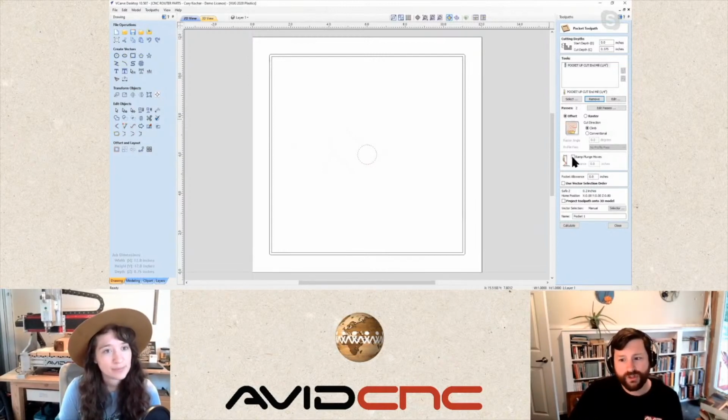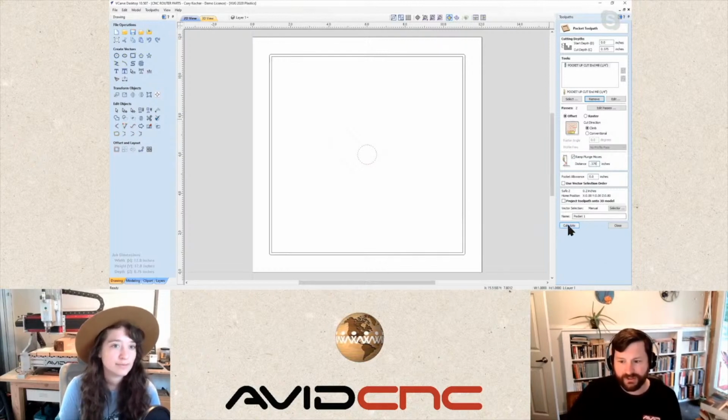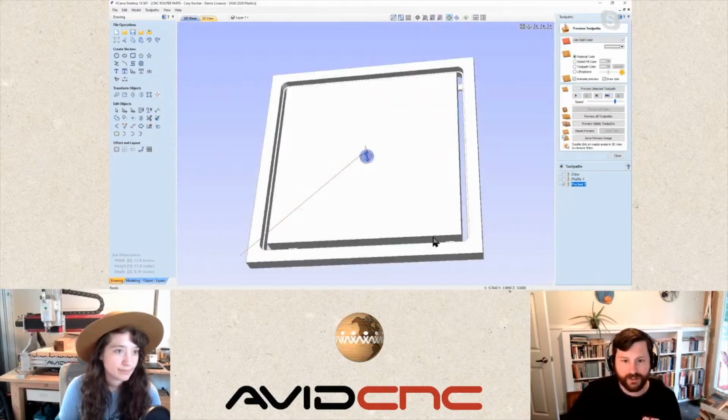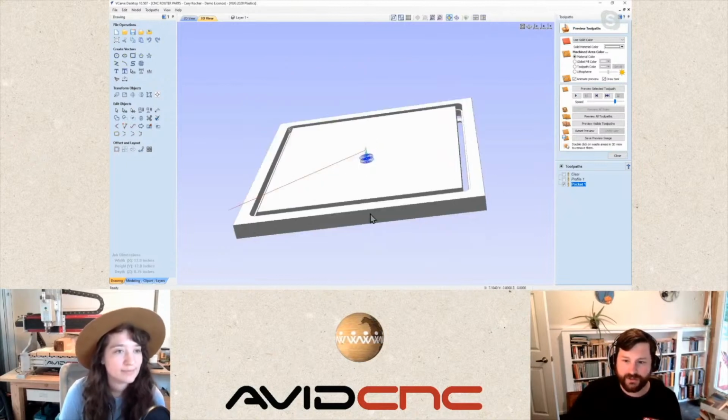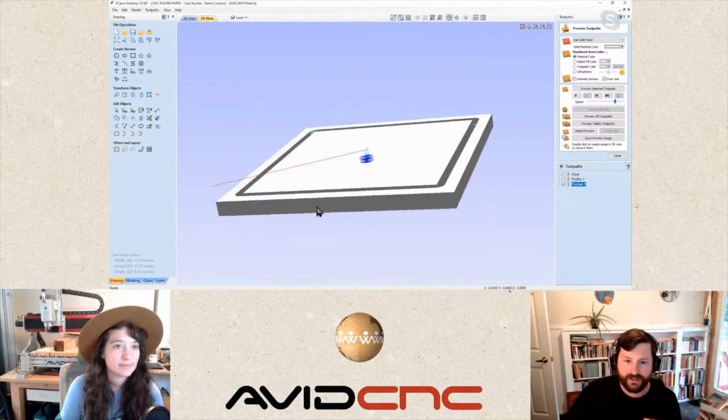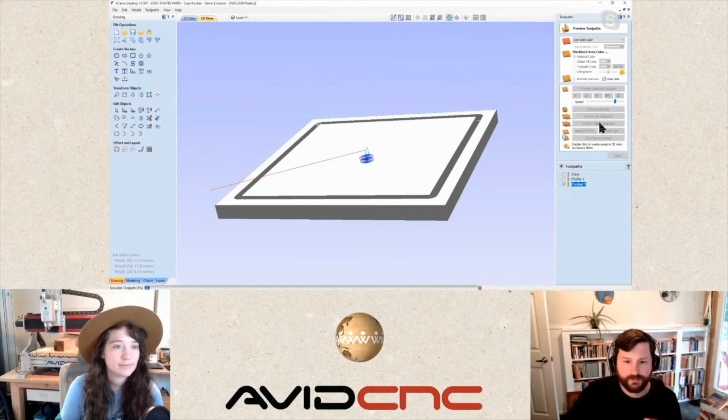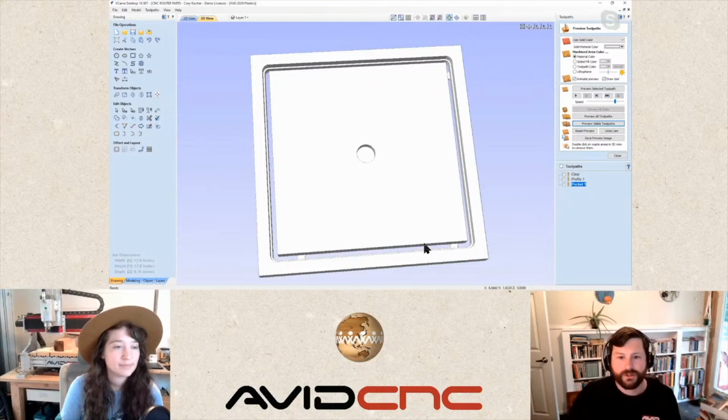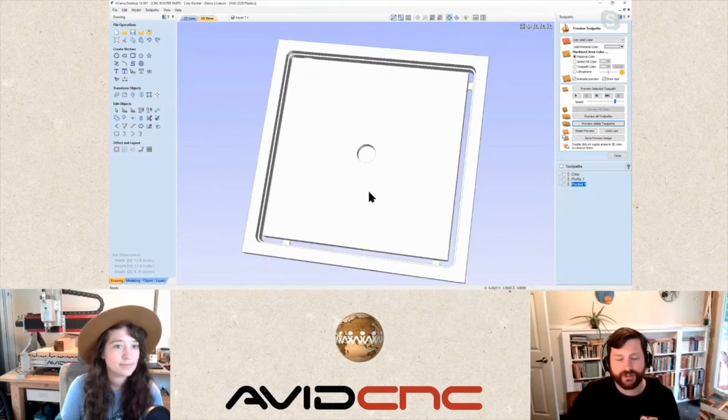Yeah, we do want to ramp this, and we'll do that same 0.375-inch ramp distance. And we don't need a pocket allowance right now, and so let's go ahead and calculate this here. And perfect. So yeah, we're doing this in a couple passes, and perfect. So good chip evacuation, pocketing toolpaths, we have that room around the tool, but let's pretend like we wanted to make this a counter bore for a through hole.